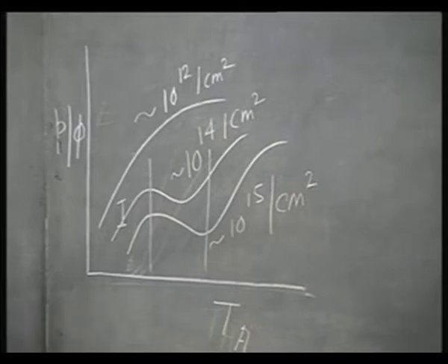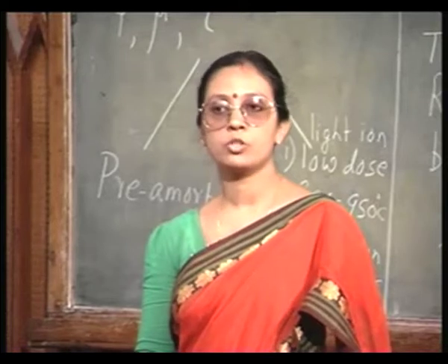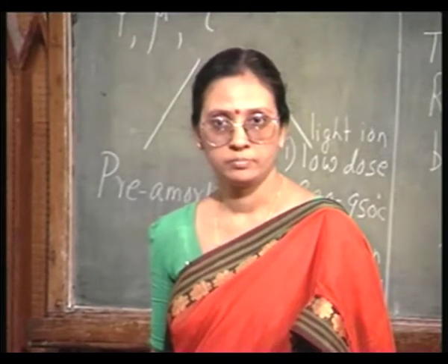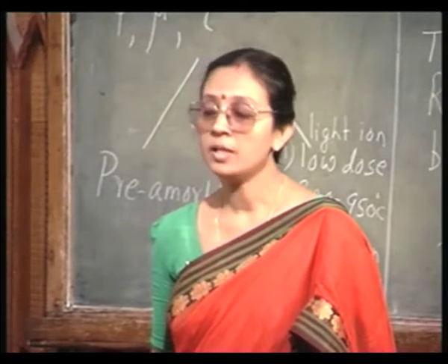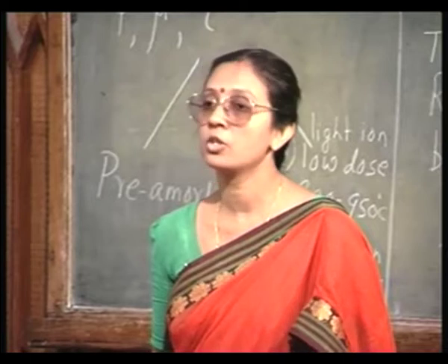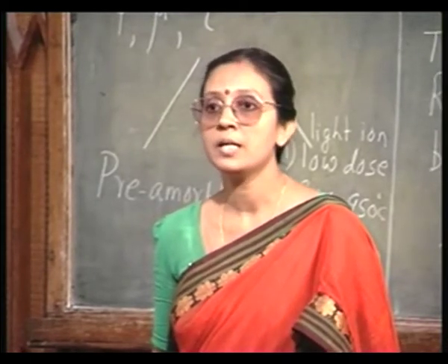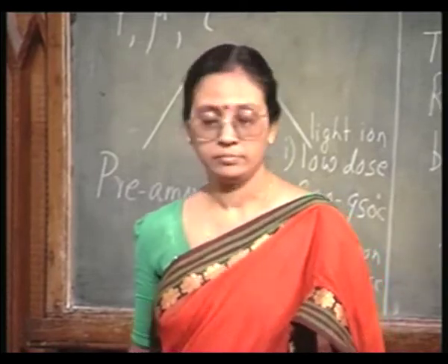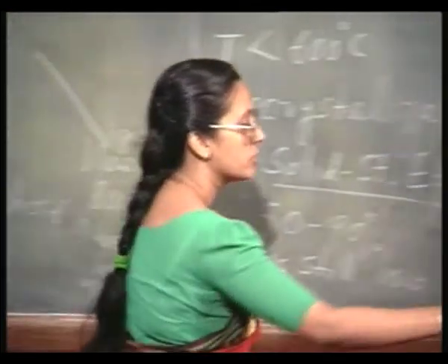Now, remember, when you are carrying out this annealing, you are also promoting some diffusion. At this high temperature, the profile can change to a certain extent. It may not remain exactly as the implantation profile. So, how is the profile going to change?